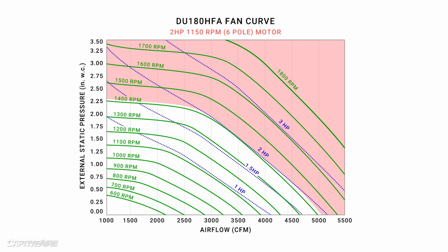Now let's get back to the example of 2000 CFM at 1 inch of static. We can go ahead and plot that in the curve. And we see that, okay, with this motor selection, we have a ton of headroom here. What I mean by that is, say this was specified for new construction, right? And in the field, once everything is installed, we end up for whatever reason with 1.5 inches of static instead. We have plenty of margin to speed up the fan and still meet the 2000 CFM requirement. But how much margin is too much margin?